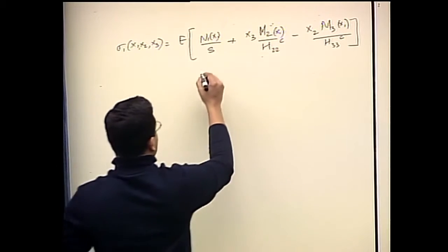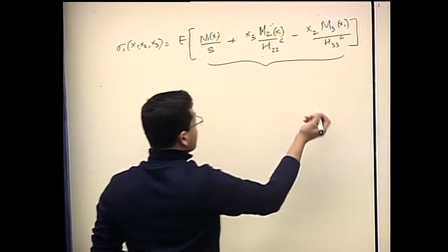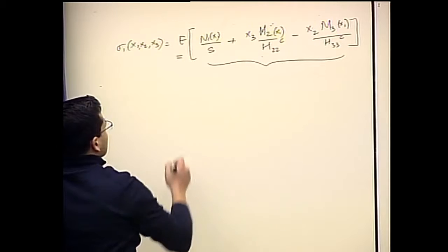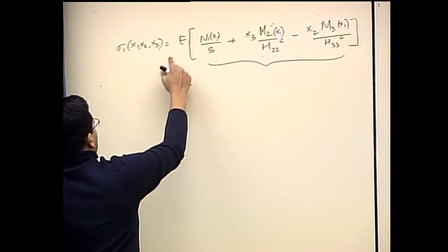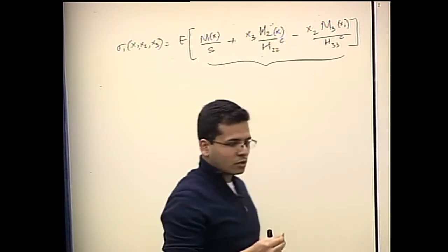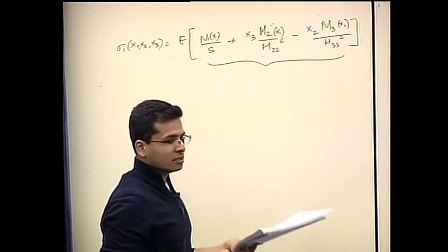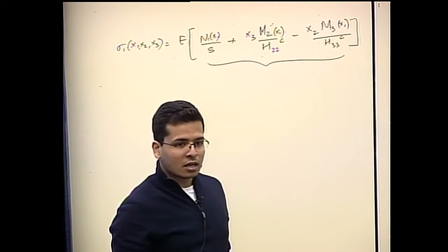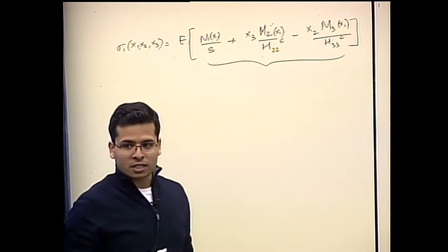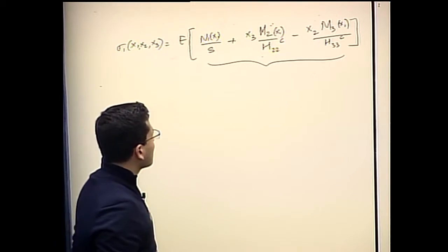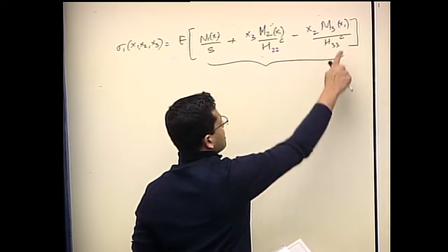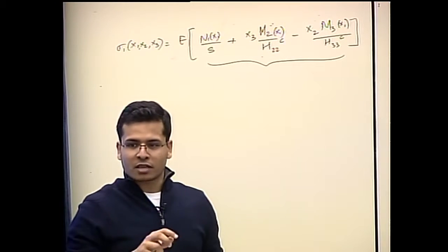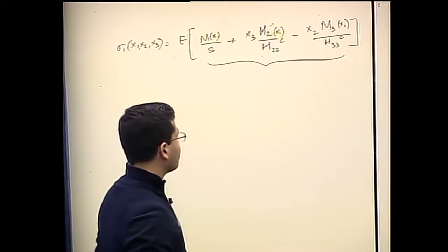So this expression essentially represents the strain measures, and we multiply it with Young's modulus to evaluate stresses. This also assumes that there is symmetry about one of these axes, x2 or x3, in the cross section. Otherwise there would be a term of H23C. And of course the superscript C means that we are evaluating these quantities at the centroid, or the frame at the centroid of the cross section.